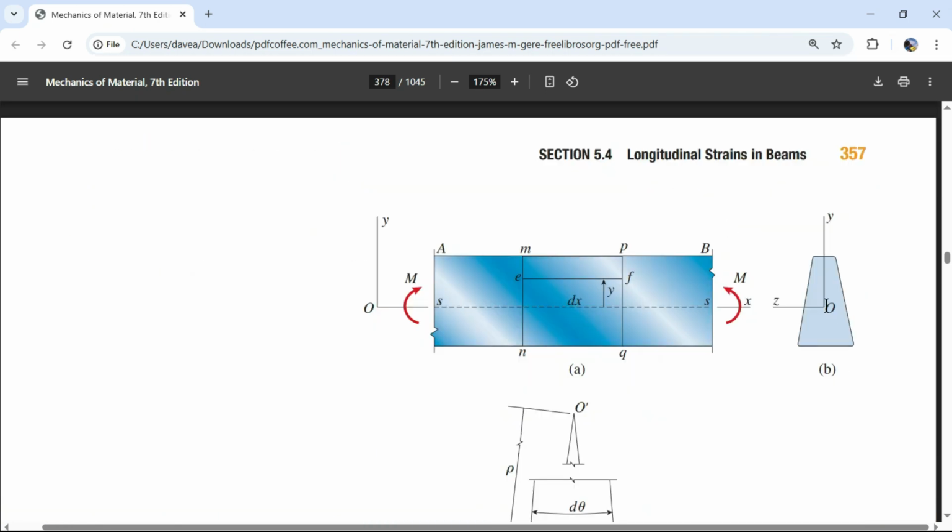So we're gonna have crunching up here, but check it out. What did we say? We said that if we have crunching up here, it's going to be bulged out. If this is a cube, where this left face and right face, and we're just taking this slice up here. You know what I mean? So just imagine a small little cube right here where this left face and right face are being compressed together.